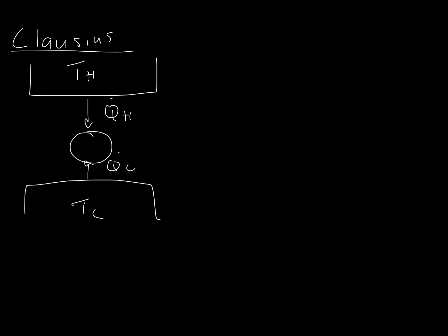I just drew it in that way to make it so the math should work out. Ultimately, when you do these energy balances, a lot of people stress a bit much about whether work is positive going into the system or positive going out of the system. I never care that much. All I care about is that whichever way you draw your arrow, you're consistent in your own energy balance. If the arrow is being drawn in for Q, it's plus Q. If the arrow is being drawn out for Q, it's minus Q. And so when I ask a question like on an exam, if I say, what is the work output, I will want you to say blank kilowatts into the system or blank kilowatts out of the system.